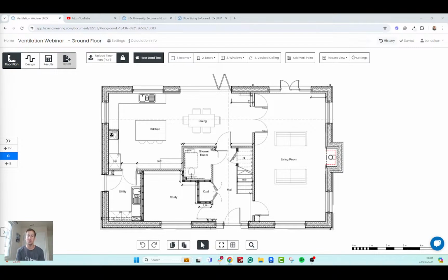And while it will be very focused on the new feature, we do also have other mechanical engineering systems too, so you can design heating and chilled, do all your heat load calcs. We have a range of plumbing calculations too, so hot and cold water, gas, wastewater and stormwater, and a range of fire systems too. So you can design sprinklers and hydrants, hose reels in ring main formations and things like that. And there is a lot of exports too, but we will cover those today.